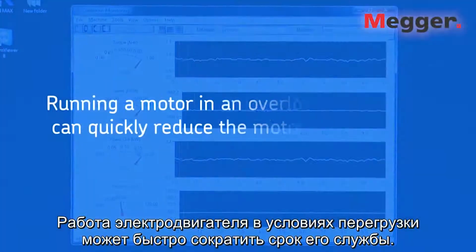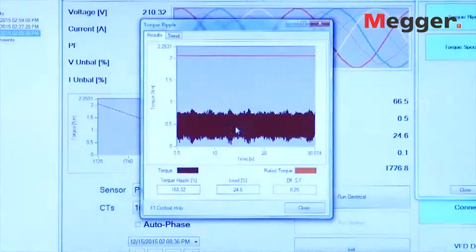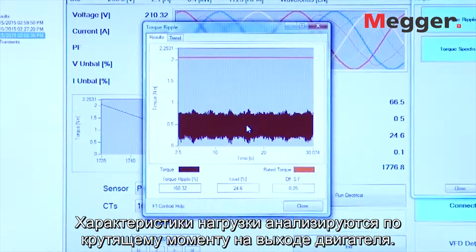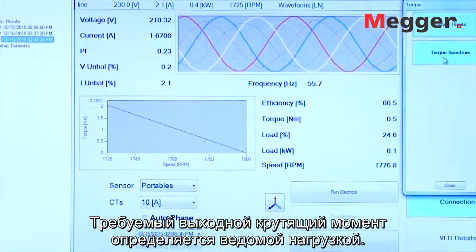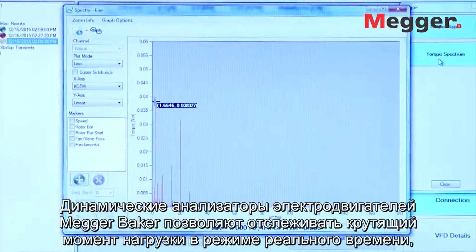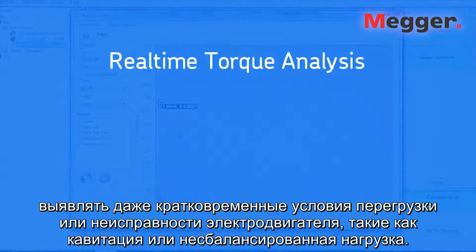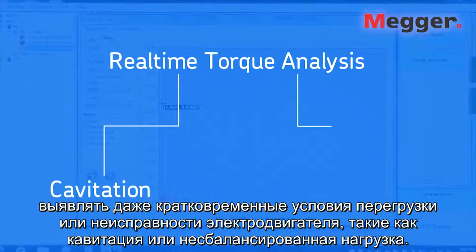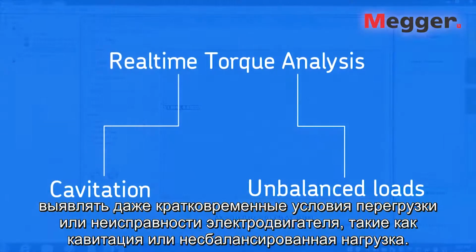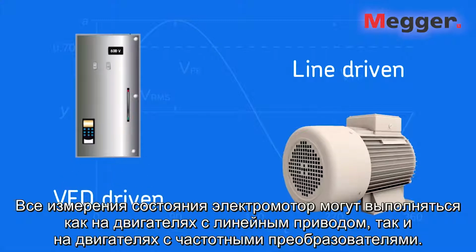Running a motor in an overloaded condition can quickly reduce the motor lifetime. The load performance is analyzed by looking at the motor torque output. The output torque required is determined by the load. Baker Instruments dynamic motor analyzers allow you to look at the load torque in real time to find even temporary overload conditions or machine faults, such as cavitation or unbalanced loads. All operating point measurements can be done on line-driven and VFD-driven machines.